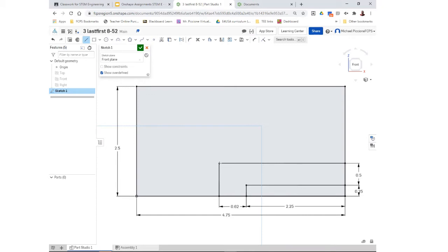So first we wanted to continue this line over. And then we knew we had a sloping line somewhere in this region. It started somewhere around here and ended somewhere on this top line, but we don't know exactly where, so we'll dimension that. Let's dimension where it starts. From the left edge of our drawing to the point the line starts, we said it was 1.25.